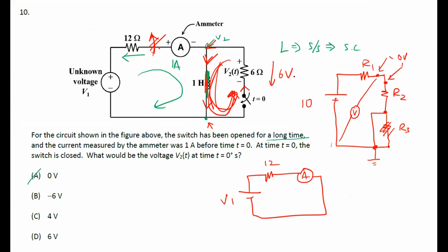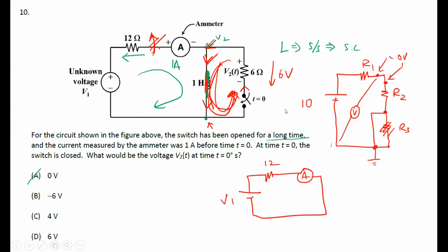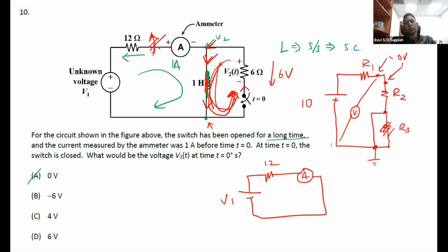Oh, so in time, would the current go the other direction? No, it will just carry on in this direction, it will decay. Oh, means the inductor's current direction will not switch. No, it won't change. Then in what circumstances would the current change? It will not change unless, when it is in the transient state, you make it flow in the opposite direction, then it will change.